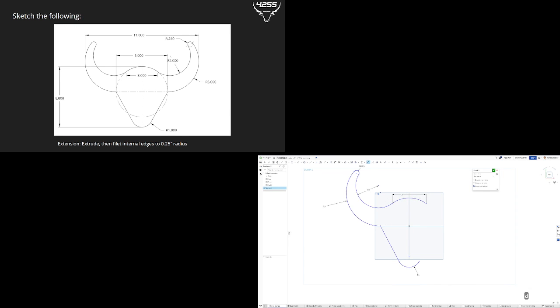And finally, the dimension that I was talking about that I think I'm missing here is the radius of the top of the head. I think this is going to be necessary in order to constrain everything, so I don't know what it is, but I'm just going to go ahead and leave something here to define it. Also, there's one more dimension I'm missing, and it's 5 inches apparently, from the corner of this arc to the corner of this arc. So that means that the overall radius of this circle, oh, I guess I'm not missing a dimension. The overall radius of this circle must be 2.5.